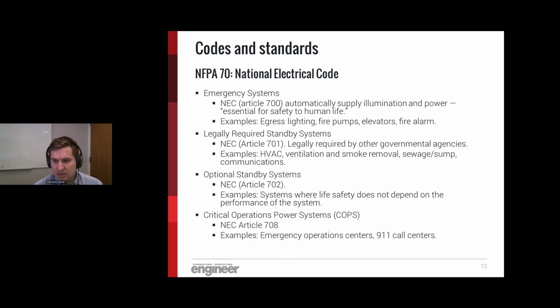And this last one here is the Critical Operations Power Systems, NEC Article 708. So when we talk about public mission critical facilities, this is the best example that I can give. If you're designing a project with an emergency operations center or a 911 call center for a public entity, a county or a city, more times than not, the systems that you'll encounter would follow the requirements of this NEC Article 708.